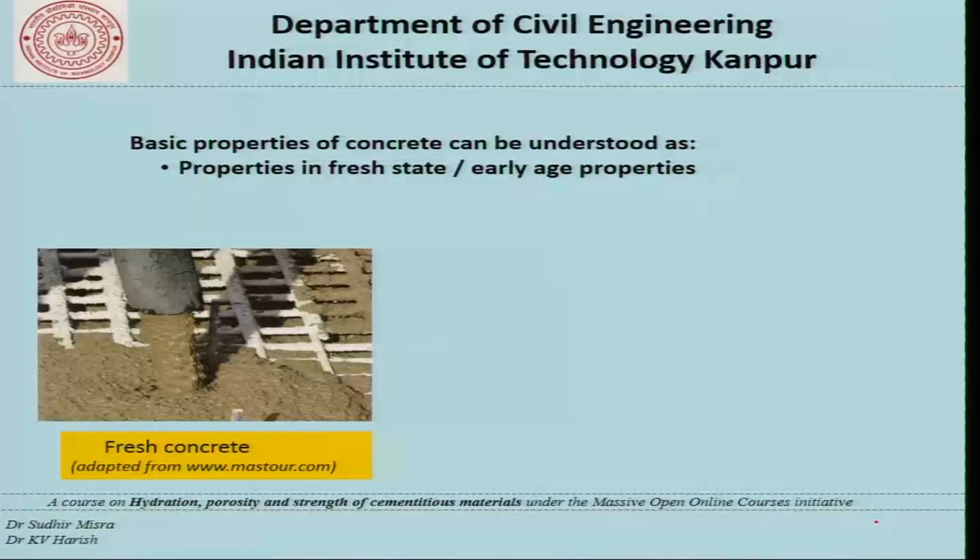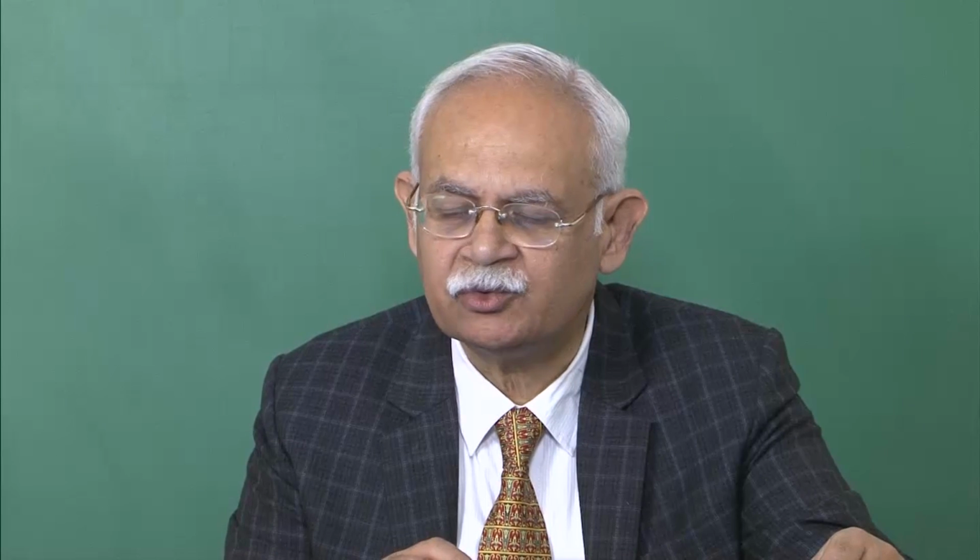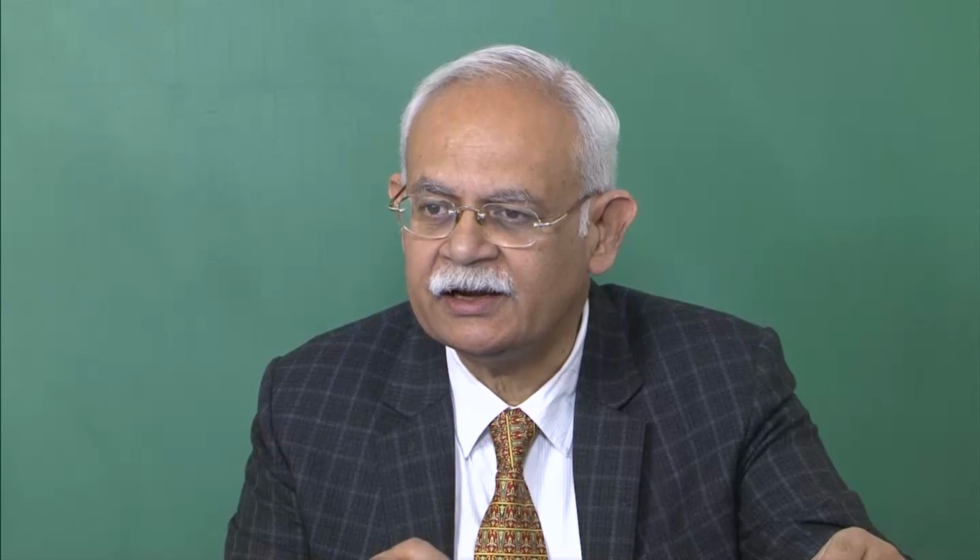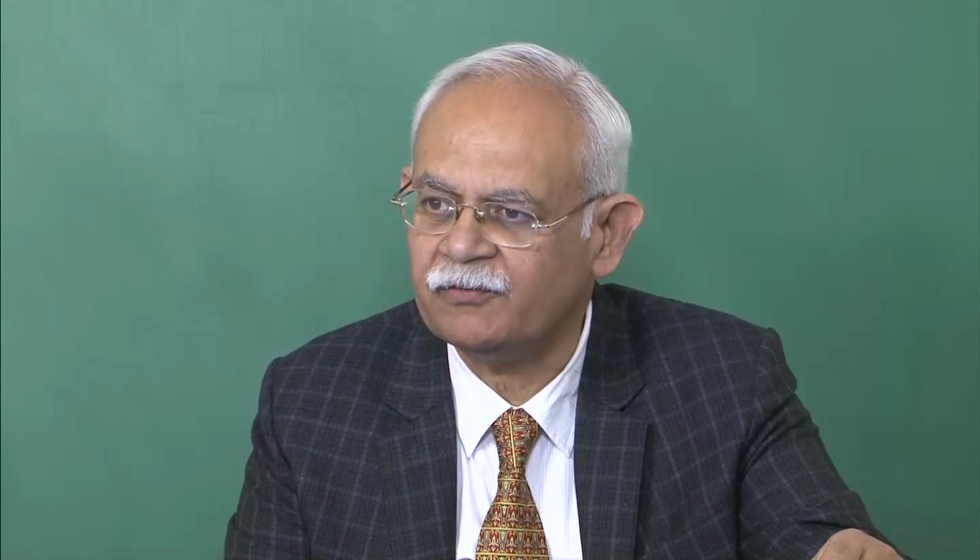So now, in the fresh state, we expect concrete to largely behave like a fluid, as is shown in this picture. We expect concrete to go through the reinforcement that is shown here and fill up all the gaps. That can be done with some amount of help through consolidation. Otherwise, we now have self-compacting concretes which do not require any compaction and take whatever shape the formwork has.